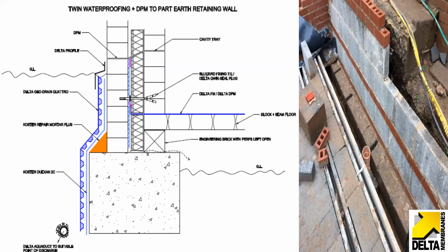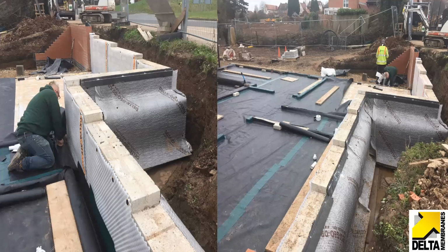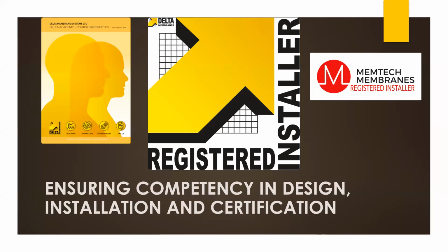So that's a house into a hillside. That's the real life photo of that. You can see the two systems, Type A on the outside, Type C on the inside. And the Type C drains into the subfloor void, and that's made drainable and maintainable as well. So that's a good detail.